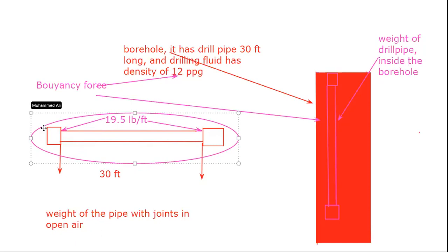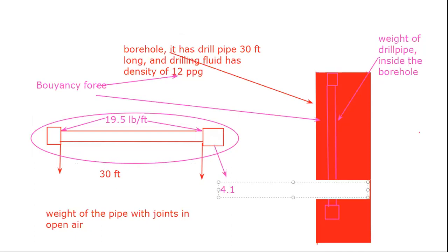In order to adjust the weight of the tool joint, we must know the type of tool joint we are using at this point. Which kind of tool joint do we have? Here we have a 4.5 inch IF connection. We have a long list of tables with different pipe sections and different tool joints. We have the nominal weight, and based on that chart, we find out the weight of all this drill pipe per foot. This is what we are doing.